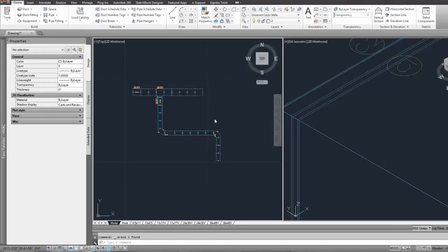So I thought what we would do today is, we spoke a little bit about it in the past, display themes and the power of display themes and what benefits you can get out of them. Display themes display your AutoCAD MEP objects in different ways based on a set of criteria that you define. Our software comes with a couple preloaded display themes that are mainly used for the Revit to AutoCAD MEP fabrication. But today I'm going to speak about creating some new ones for use in your general day-to-day modeling.